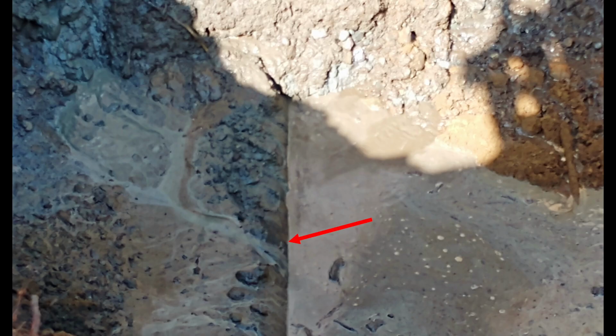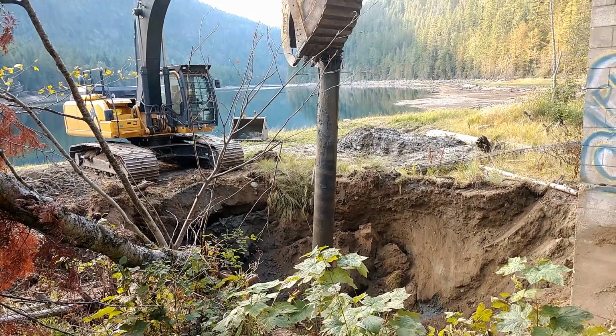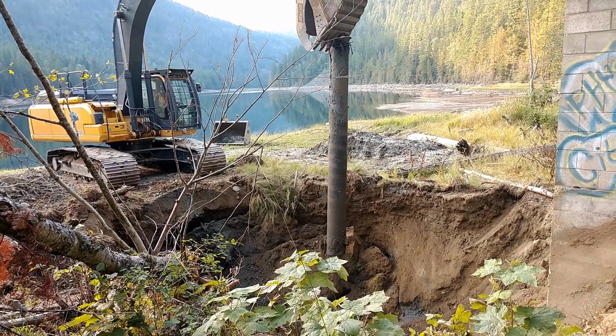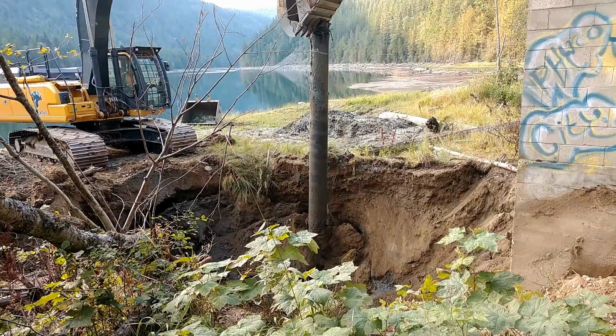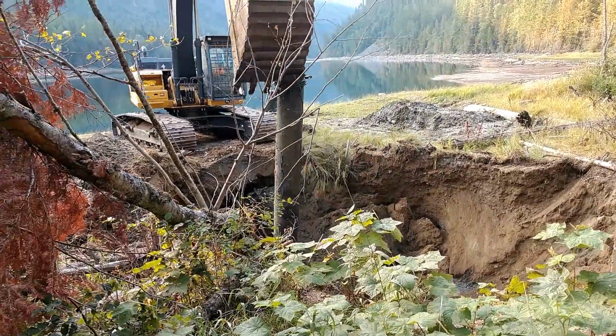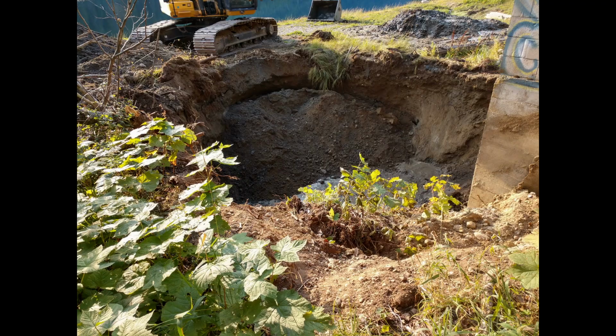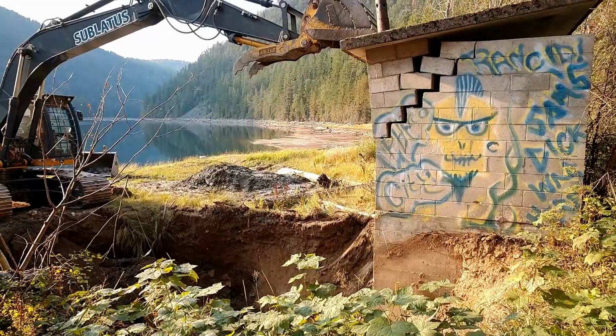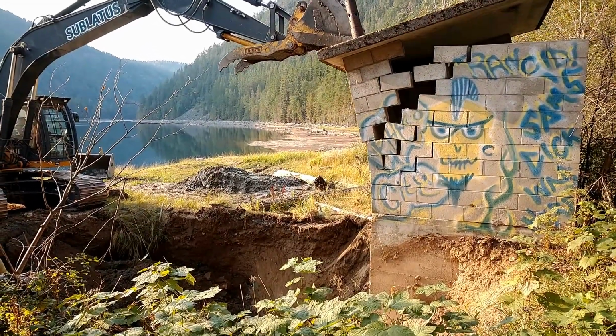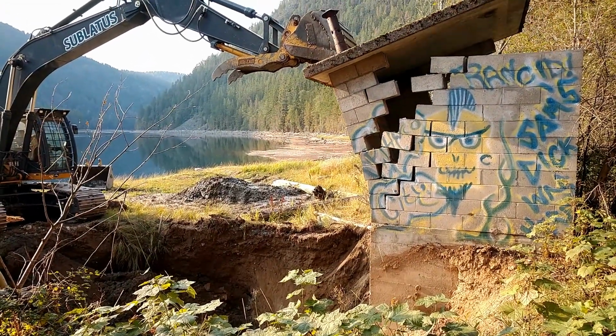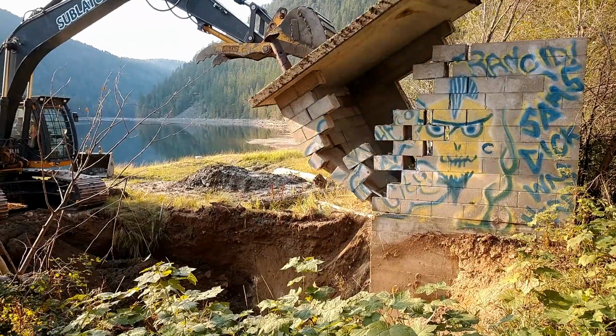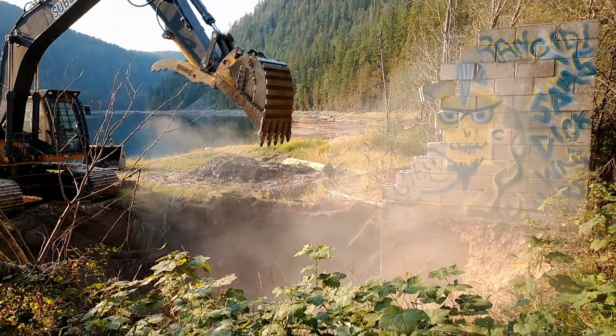The siphon pipe that is surrounded by groundwater at the bottom of the hole is marked by the red arrow. We removed long sections of the pipe so the siphon could no longer be used to drain water from Violin Lake into Cambridge Creek. Soil was placed in the bottom of the hole and compacted to prevent water from entering the pipes that were left in the ground. The excavator collapses and buries the concrete block valve house into the hole. The concrete blocks are clean fill, much like rocks.